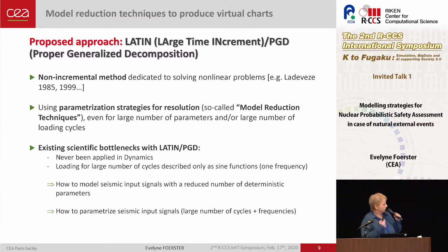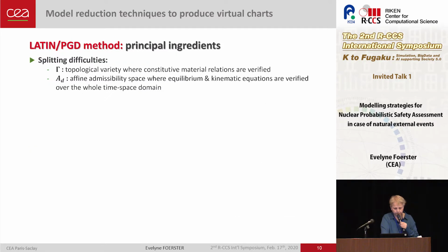For instance, if we deal with static loading, it's not a problem, but dynamic loading like earthquakes is still a problem. It's never been applied in this domain. And loading for a large number of cycles is usually described in a very simple way, especially for dynamic loading, which is not coherent with the seismic loading with respect, for instance, to the number of frequencies we have to deal with, and also with the seismic input signals, which can be very different.